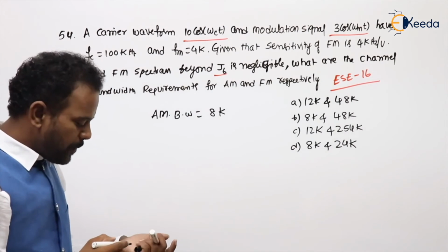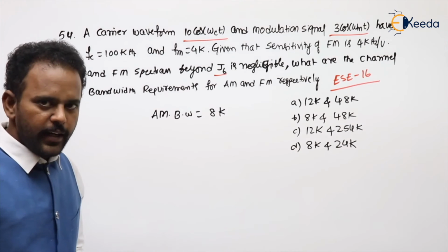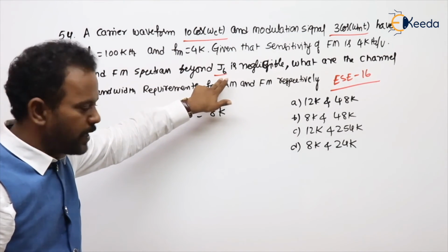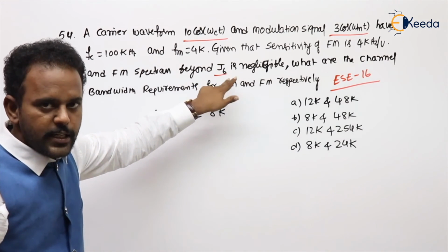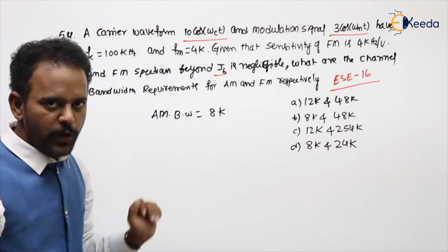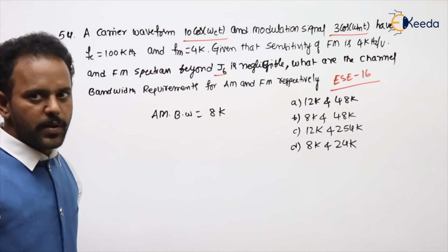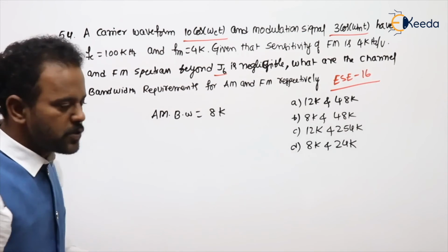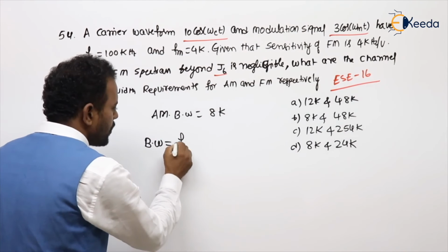And coming to the FM bandwidth, there is slight logic. Here you have to take beyond J6 as negligible. So beta is approximately 6. 2 into (beta plus 1) into f_m, if you do, you will get some 56. No option is given. Another possibility is here. Components beyond J6 are negligible. So I can say bandwidth equals highest minus lowest.